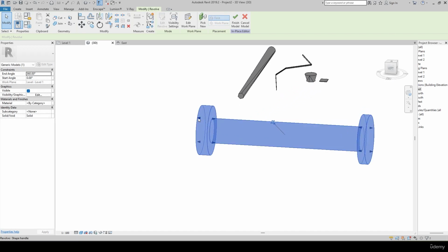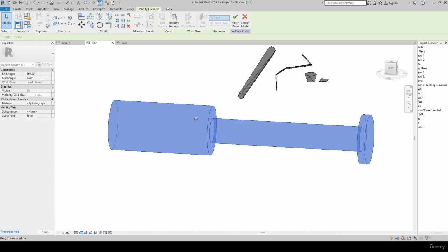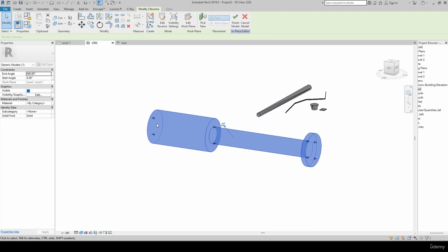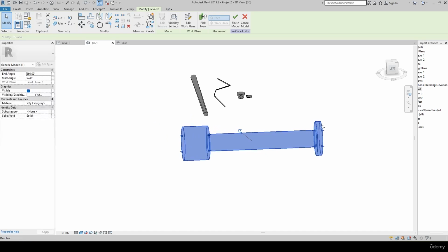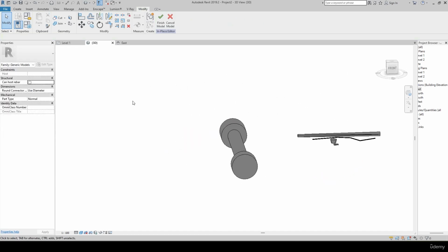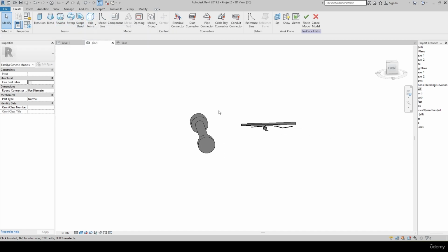See here again, you can drop the customize, cancel, go to the left side, go to this. Maybe if you want, you can just do this, or else I'll take this much. So now you can notice this kind of structure or element. If you want, you can design it using the sweep or revolve option.